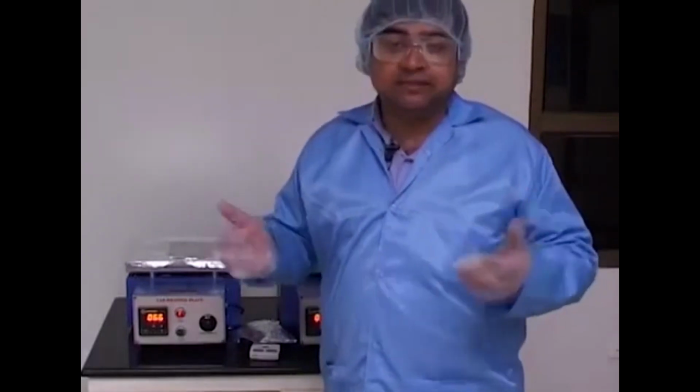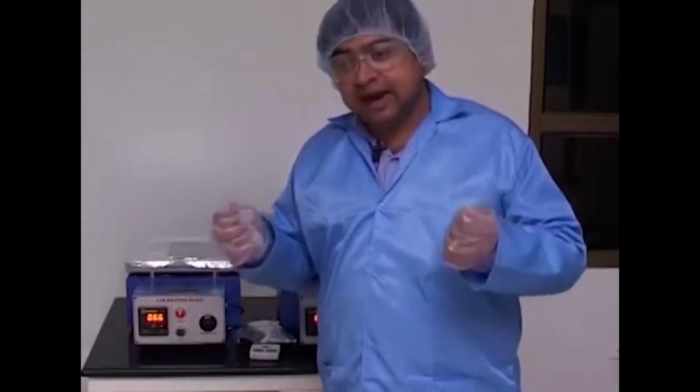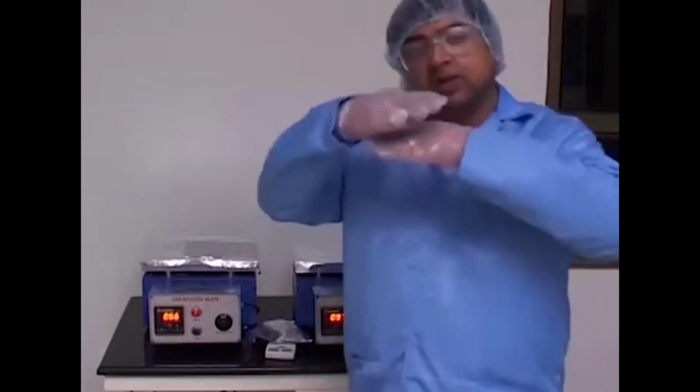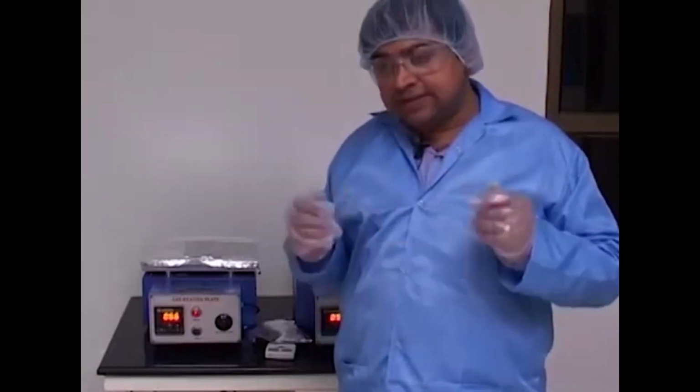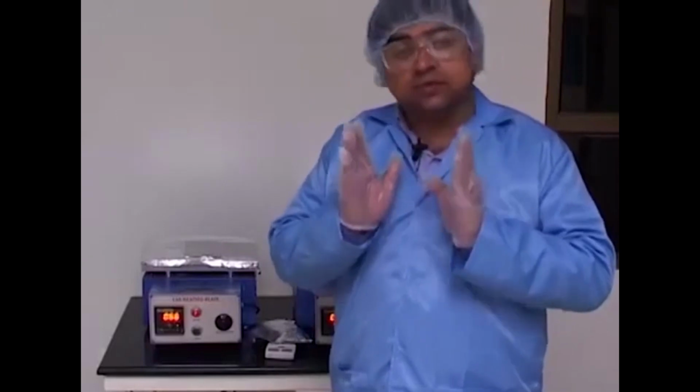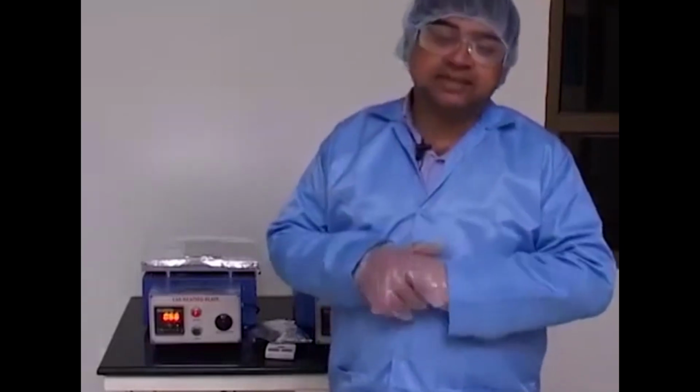And then we need to get rid of this solvent, because that would ensure that the resist film is stable, it is hard enough, it is kind of cross-bonded, and before doing exposure this is very critical, because the mask would sit on the top of the resist. So if there is some undried portion or uncured portion, the resist is going to get damaged, and that is something that we do not want, because that would mean that the surface of the micro features that it would result in will also be damaged because of that process. So we need to ascertain that the resist is fully cured before taking it to the next exposure step.